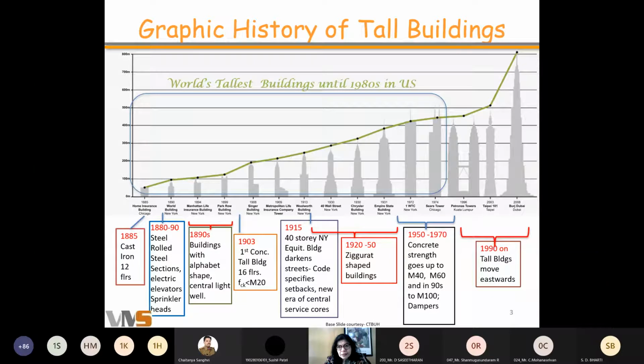If you know cast iron, it's like building with children's wooden blocks, or building a house of cards. It cannot be built with any kind of rigid joints, and there is no monolithic construction. There's no welding you can do to cast iron, and all you're doing is working with nuts and bolts. So there's a certain limitation with the material.